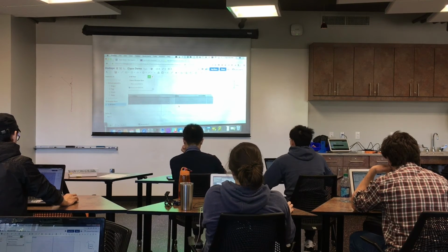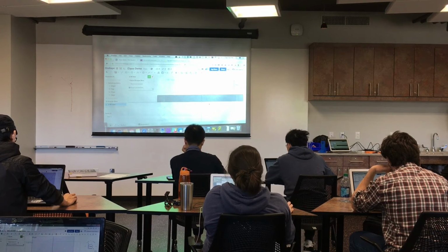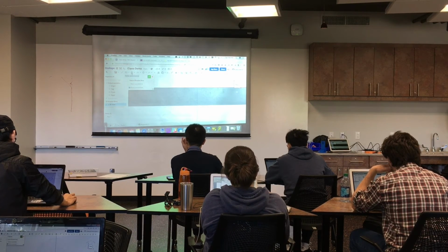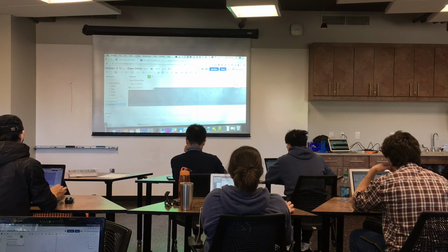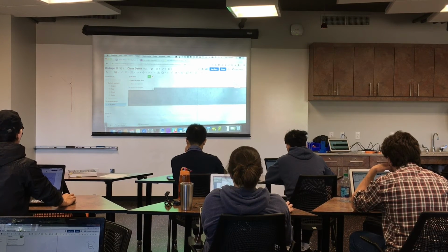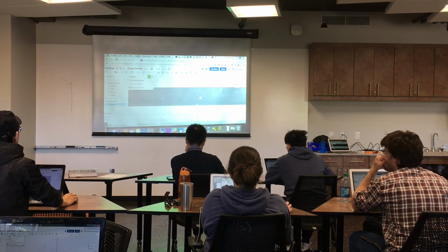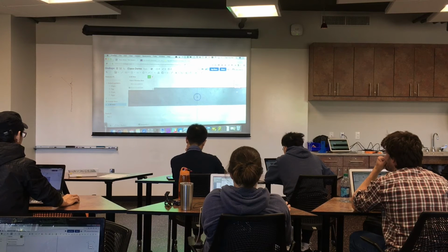So now we're sketching, if you hit N, we're sketching on this face. And we want to put a center point circle. And you can kind of mouse over the origin and then go up so that we're constrained to be on that vertical line, and drag a circle on there. So now I've got this circle that is constrained to be in the center of the part and of some unknown size. Does everybody have that?